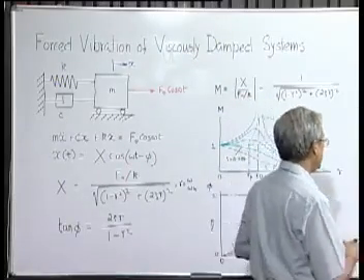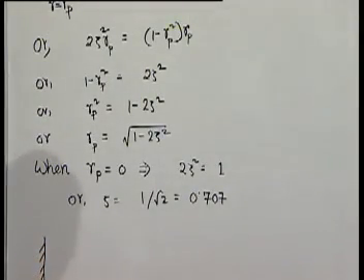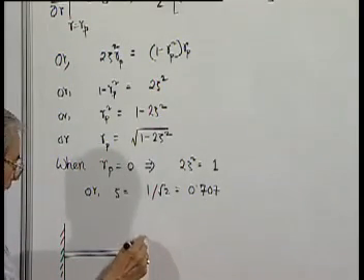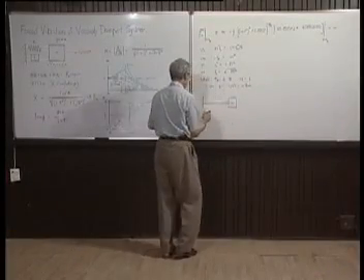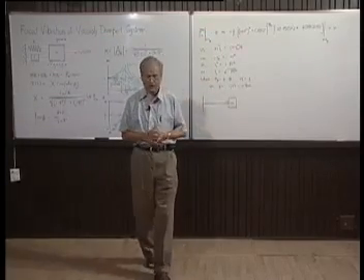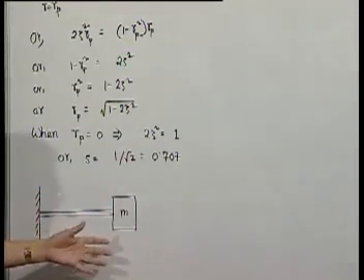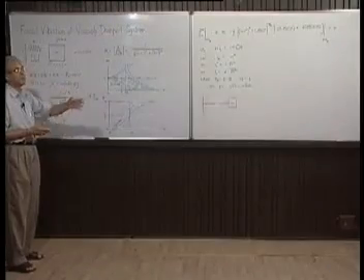Suppose there is a cantilever beam carrying some kind of a mass here. If a load is applied here statically, the stress which will be generated, or strain which will be developed, will be much less compared to the static situation if the same load is applied at a much higher frequency. So this is a very important observation,